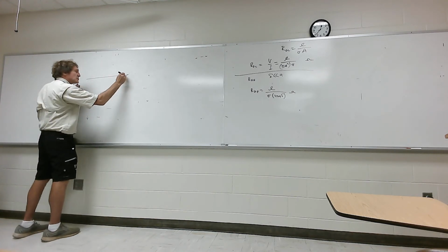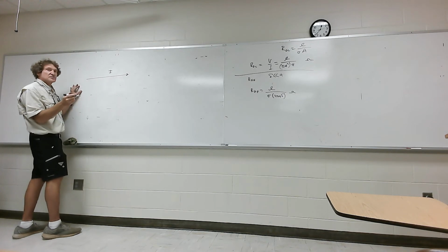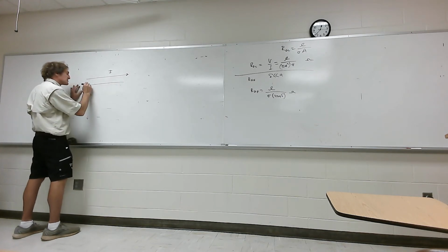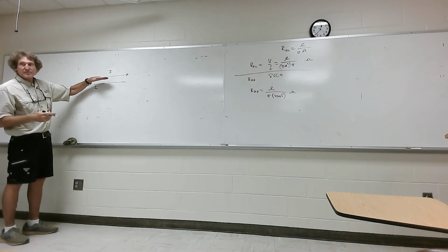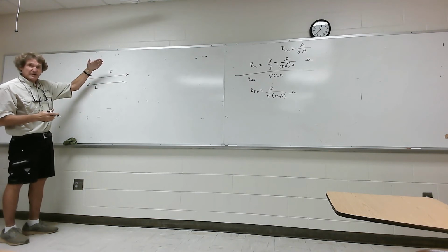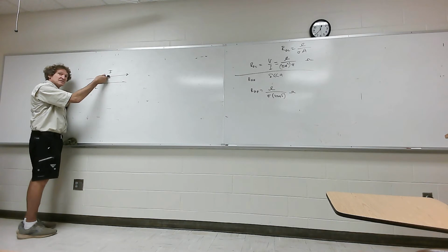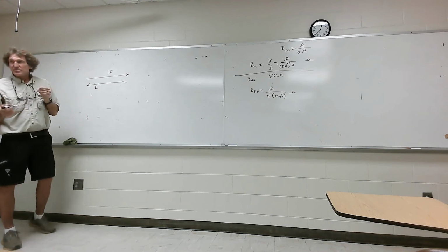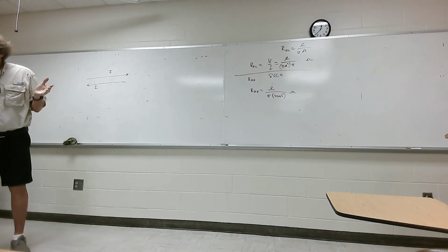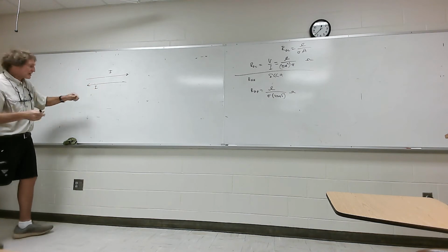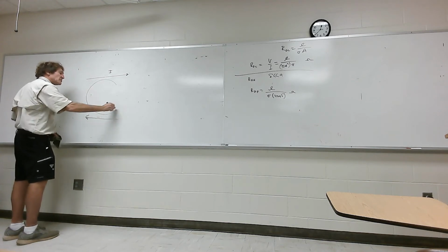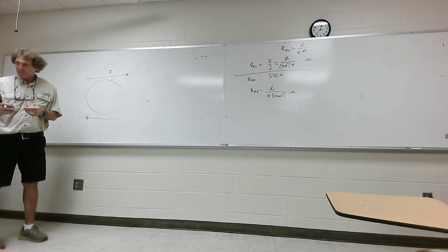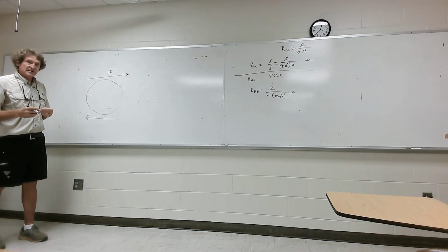Now, let me do it this way. If you take a look at just a two-wire pair, if I have I this way, and these are always driven in differential mode, and I have I this way. Right? The closer these two wires get to each other, the less the magnetic energy in the surrounding area. As a matter of fact, when I overlaps this one, there is no magnetic energy. Do y'all follow me, class? Because then there's no current, technically. But the external magnetic energy that you have has to do with the separation distance of these wires. And if I just take a wire there and a wire here, there's a huge area where you can have an H field that's significant between those two things. It'll have a tremendous amount of magnetic energy.